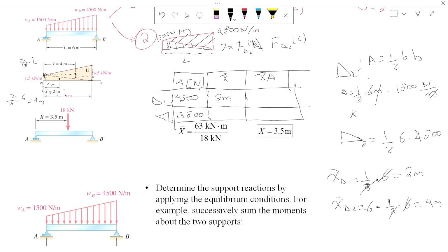If you do it from the base, but you need to go back, you do the whole length minus the 1/3, or simply remember that in a triangular shape, and it doesn't have to be a rectangular shape, it's just any triangular shape, because the area will balance out the height, is base, height. The centroid is 1/3 of the base, in this case the height, right, because we're going up from the base, or from the top is 2/3 of the height. This point can be computed from both ends.